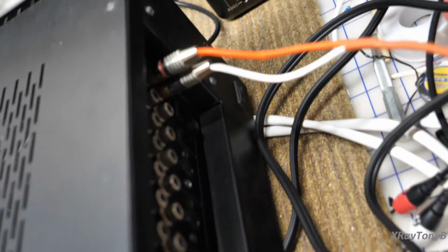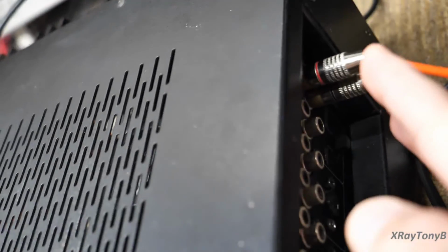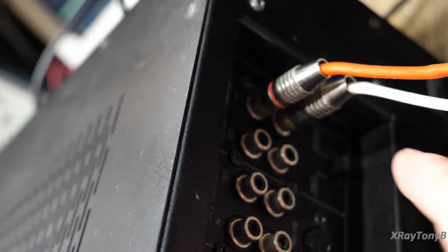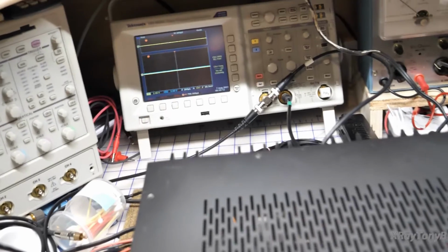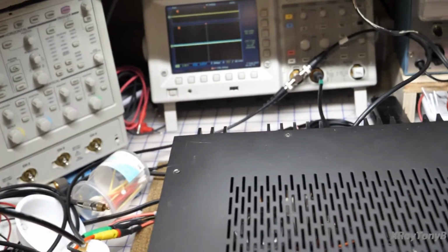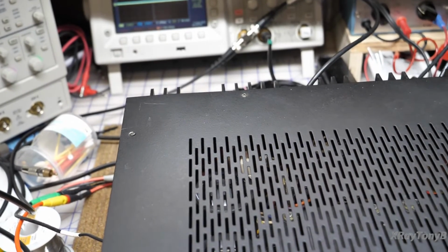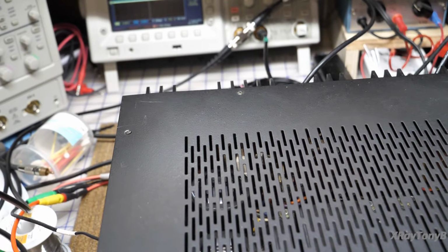Okay, what I've done is I've unplugged the signal generator from the auxiliary input jacks, and I plugged it into the main amplifier input jacks here. And I've separated the preamp section from the power amp section by flipping this little switch. Now, you've seen this on the Pioneer and Marantz and everything. A lot of times they just have a horseshoe shaped jumper that jumpers the input from the output, and you pull the jumper out to separate the amplifier. But this one actually has a switch.